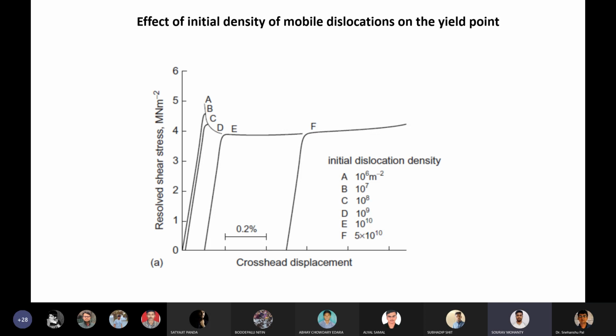So why does discontinuous slip happen, sir? When dislocation mobility is hampered due to pile-up or other sessile dislocations, slip does not continuously occur. Then again a certain stress comes and helps to reach the stress required for the movement of the dislocation.